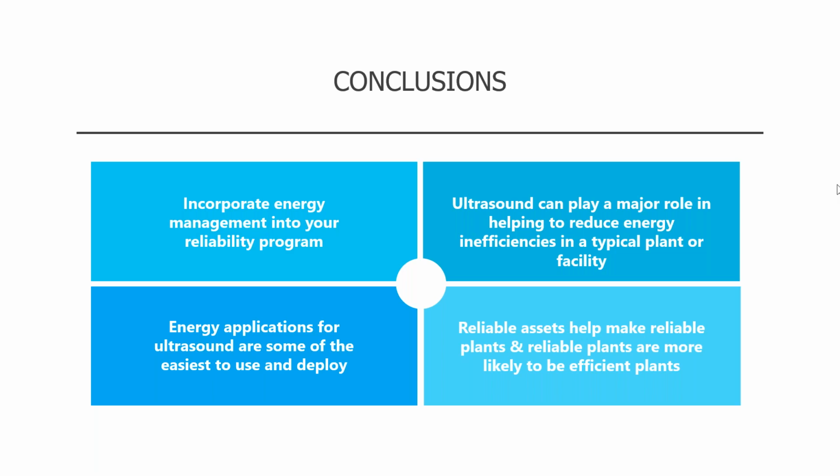So once you add in ultrasound for bearing lubrication, you'll certainly be using less grease, and there are other effects from that. So you're going to be buying fewer bearings, you're going to be sending motors out less often to be rebuilt, et cetera.